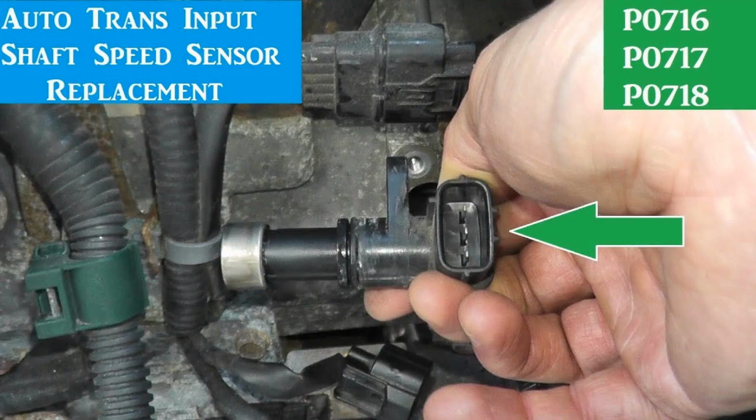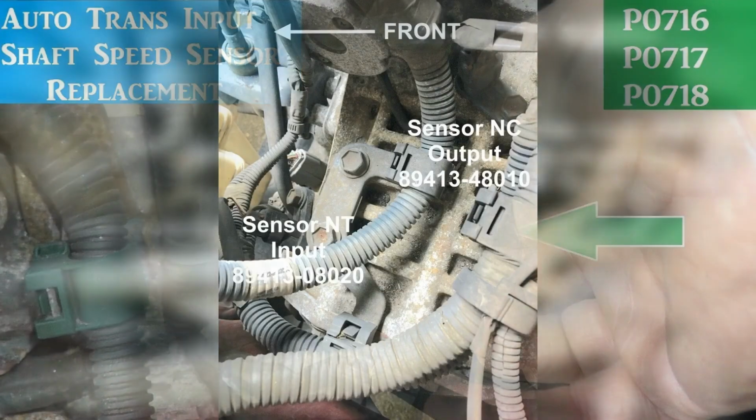A quick note on 700 series codes. 700 series codes such as P0717 are generally transmission-related codes stored by the ECM or PCM. The ECM only controls the engine, and on automatic transmission vehicles there will be a transmission control module, TCM, communicating with the ECM. A PCM, powertrain control module, controls both engine and transmission.